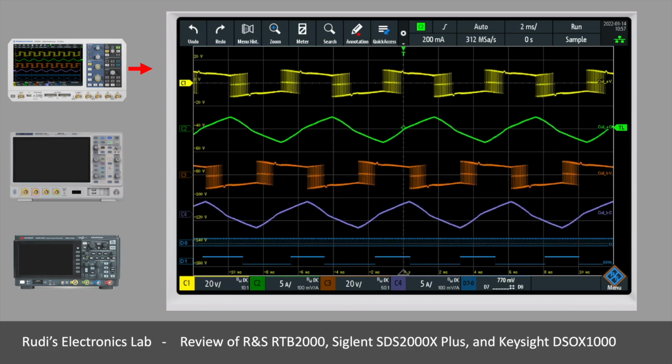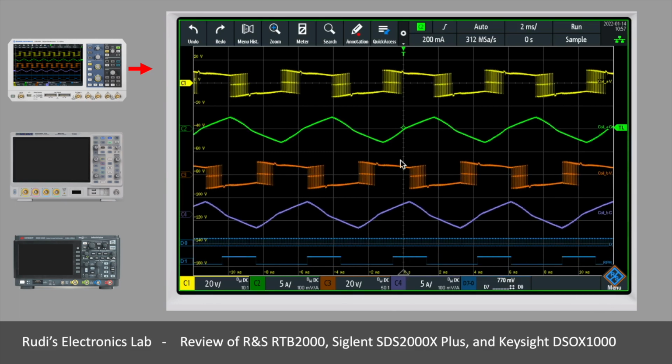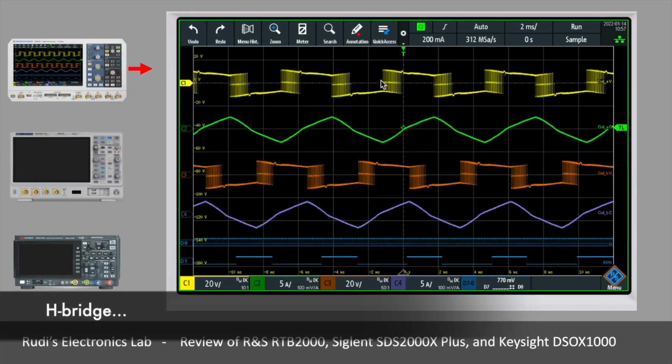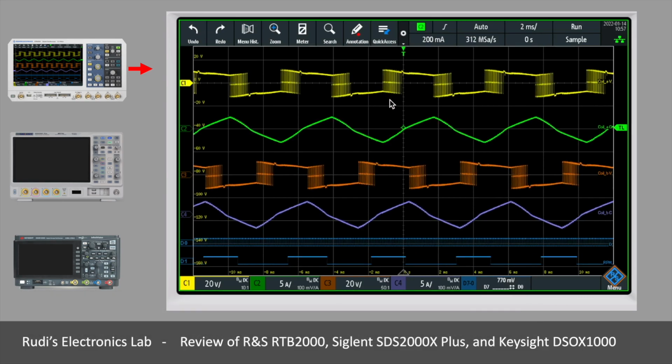On channel 1 we can clearly see the voltage over coil A, so this is an A bridge, and we can clearly recognize we got 3 different dominant voltage positions here in the H bridge. Channel B is showing us the current flowing through coil number A, and this is at the same time the channel I will be triggering to for a positive edge at the 0 value.